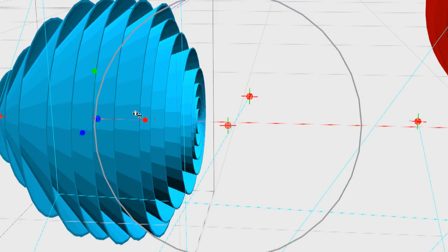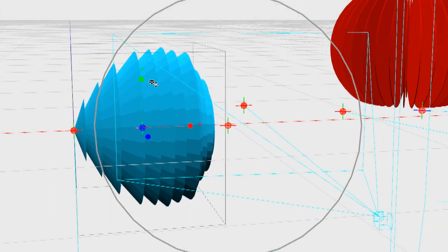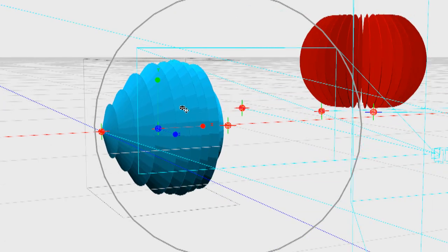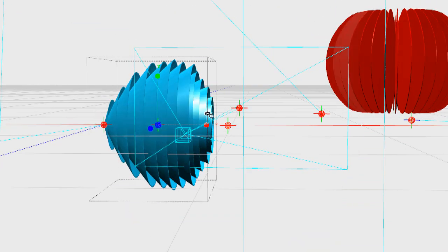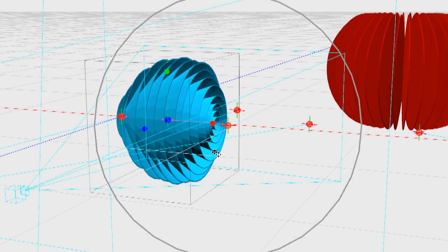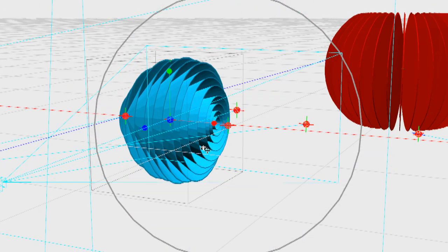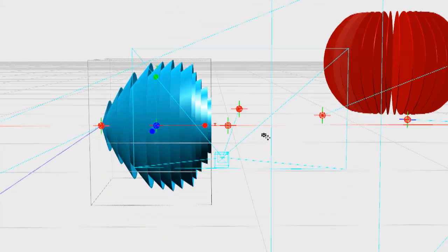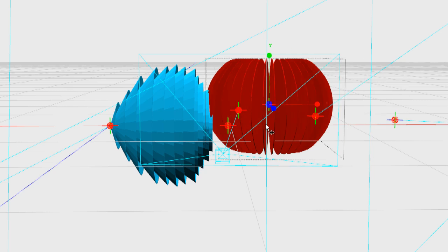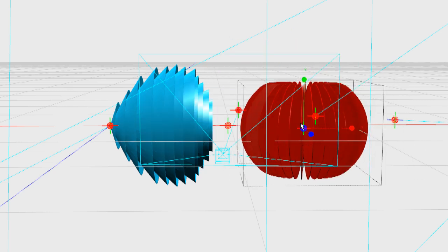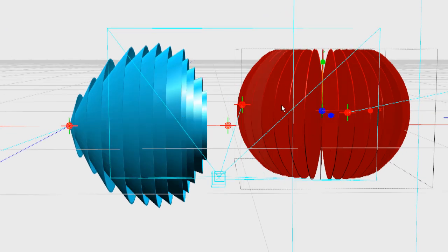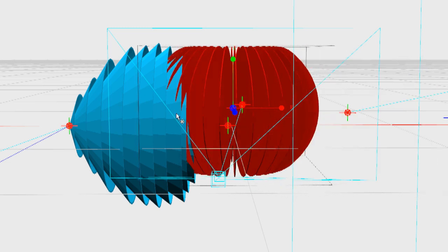So now, circularly polarized antennas are brilliant. They seem to have a much more resilient signal in terms of going through foliage and trees and obstacles compared to that of a linearly polarized antenna, such as the diversity or the rubber ducky. Now the downside is that obviously we're not transmitting a circularly polarized signal. We're transmitting, in this case, a vertically oriented signal. So there's going to be a loss because we have a polarization mismatch here.